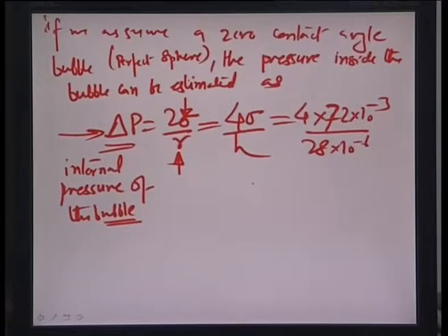This comes out to be about 10 to the power 5 pascals, or 1 bar pressure. So all the properties are defined at 1 bar, and therefore we can find the specific density of the electrolysis gas mixture of hydrogen and oxygen at 1 bar pressure. Let us go ahead and do that.